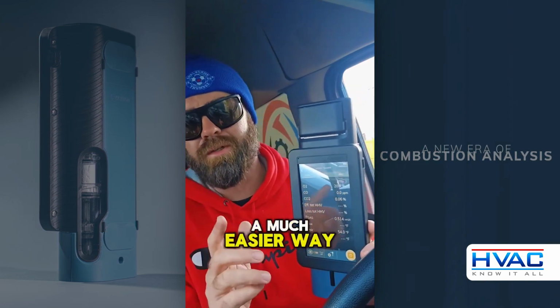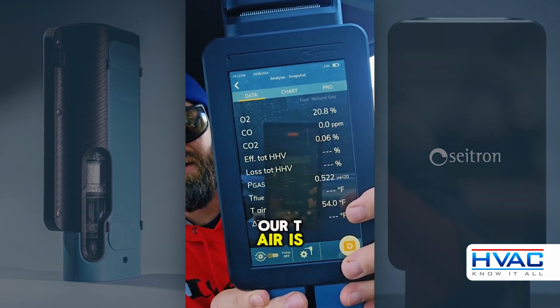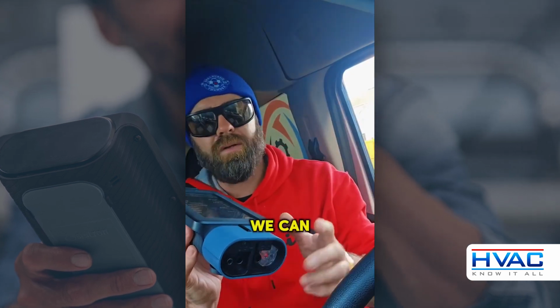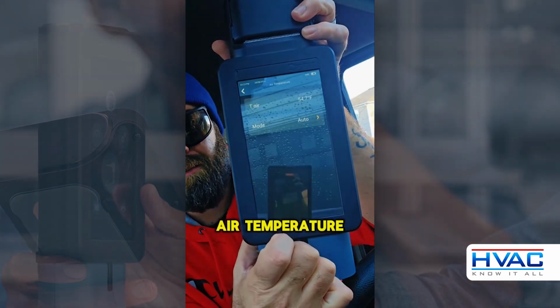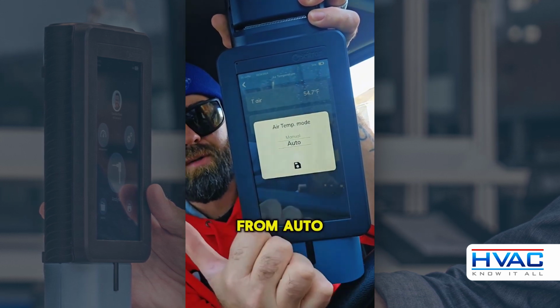I'm going to show you a much easier way to do it on the Seitron NOVO. So if you look closely, you can see that our T air is 54 degrees Fahrenheit. Instead of plugging in your Type K thermocouple, we can do it a little bit more sneaky. So the way we're going to do this is go into settings. We're going to go into air temperature. Now we're going to tap on this box. We're going to change this from auto to manual.